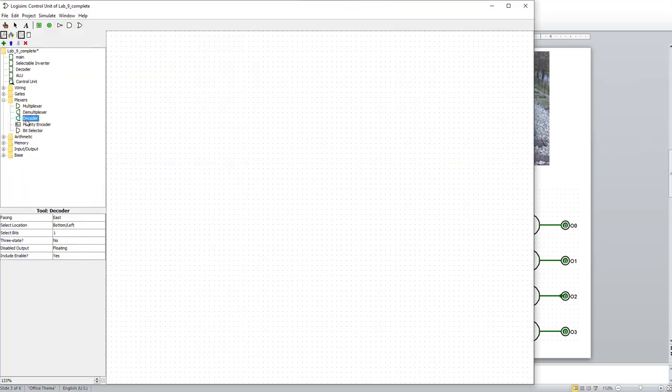You notice a decoder, this one, we want a 2-bit decoder. Doesn't have an input. This thing tells us what address to select, but it doesn't have a data input, as opposed to a demultiplexer, which has a data input.